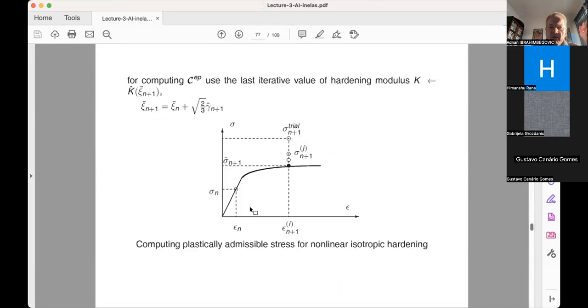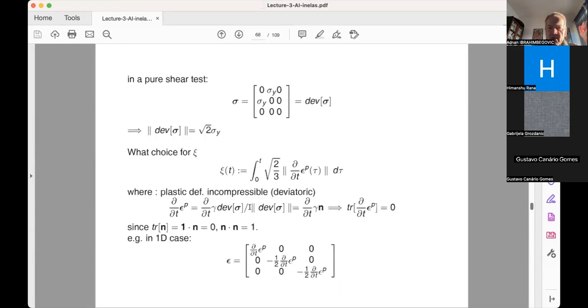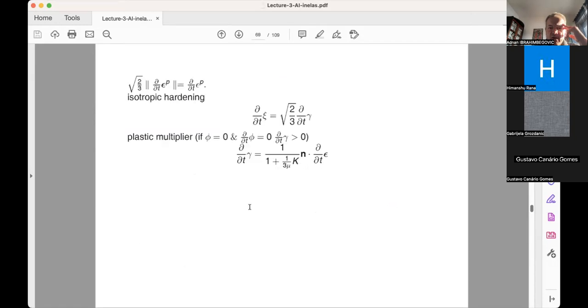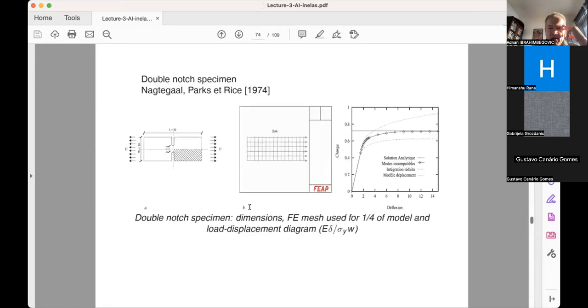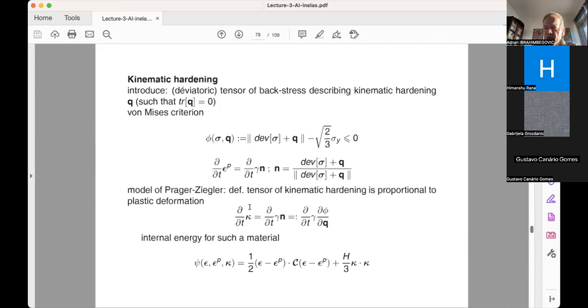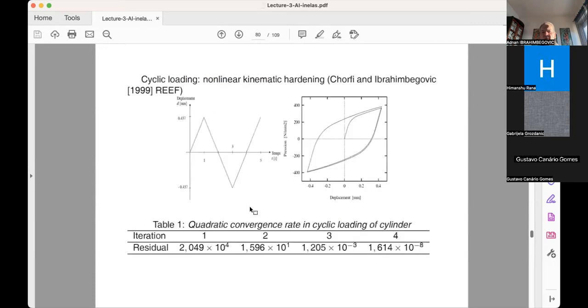So we have done everything for the elastoplastic models. We started with the one which has just a linear isotropic hardening. Then we've done something with a nonlinear isotropic hardening. Then you could do kinematic hardening. If you want to do both, there's no problem whatsoever. You can just put it together and you have more internal variables. You have to compute more, but the more the merrier, as they say. And that's the same with the rate-independent plasticity. This is kind of the final word on that.